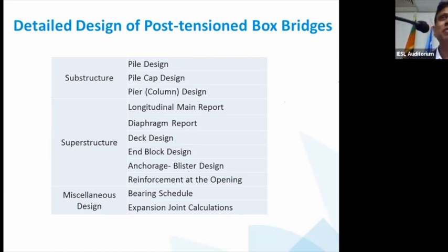That's true, because anything will be built on it. You need to know what the ground conditions are, right? If the ground conditions are not right, the structure will collapse due to a number of reasons, such as settlements and movements. So you need to work with the geotechnical engineers very well. And then with that, of course, you go to the superstructure. There are the reports, the diaphragm and things like that. Let me touch base on some of the aspects in my next few slides.